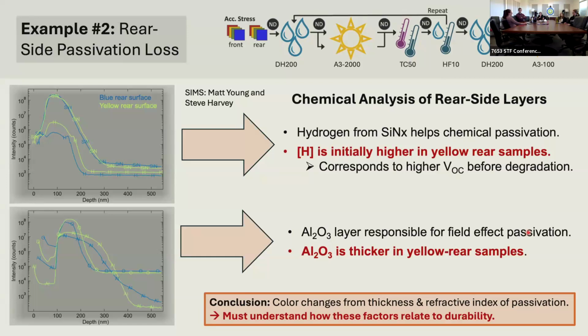I think that's really interesting. The reason that they degraded less with the rear side exposure, I think, is because they have a lower internal carrier density from the lower absorption from the rear side, so that coating is awful. They're just absorbing less light. They generate like 7 amps from the rear side or 10 amps from the front side. So the rear coating is not great. And in this stress sequence, it specifies the rear exposure is 1,000 hours instead of 2,000 hours. So we did the rear exposure test, and they degraded less than if they were illuminated from the front. There are a few reasons for that, mostly, I think, internal carrier density. You just need the charge there.